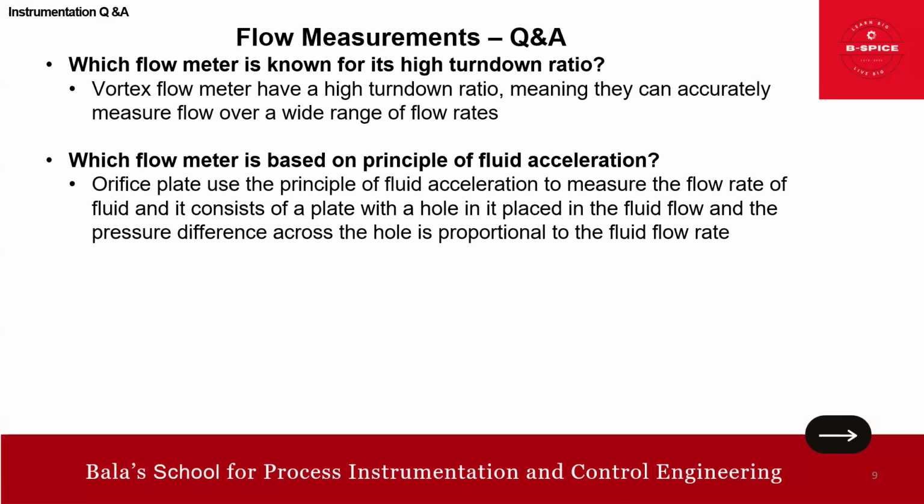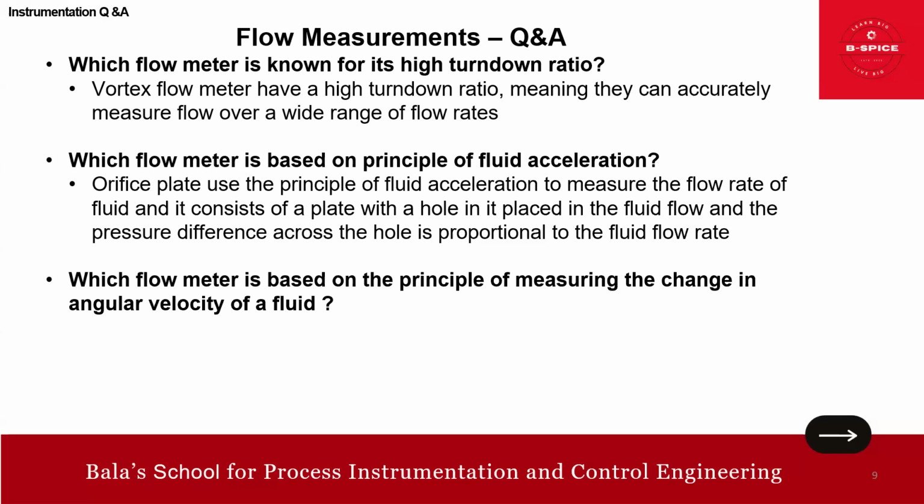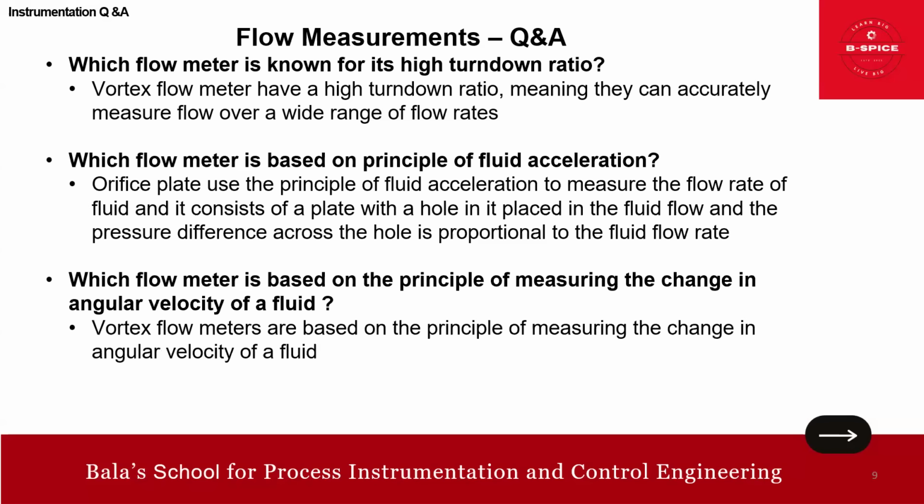Principle of fluid acceleration. You know the answer, but the question is tricky. Yes, the orifice plate uses the principle of fluid acceleration to measure the flow rate of fluid. It consists of a plate with a hole in it placed in the fluid flow, and the pressure difference across the hole is proportional to the fluid flow rate. Very simple, but the question is tricky. Which flow meter is based on the principle of measuring the change in the angular velocity of a fluid? Again, a tricky question. Yes, vortex flow meters are based on this principle.